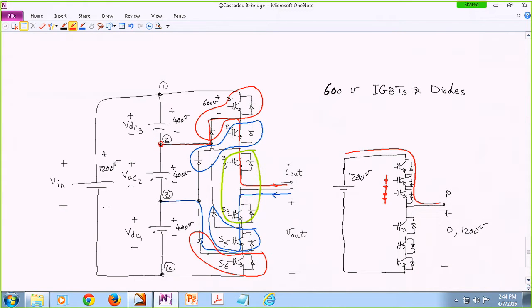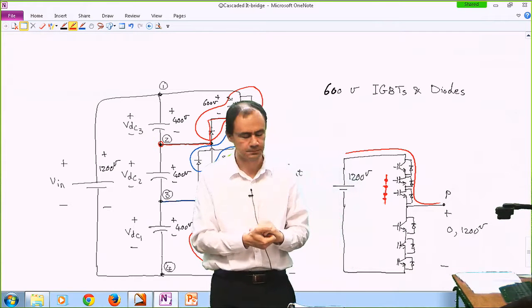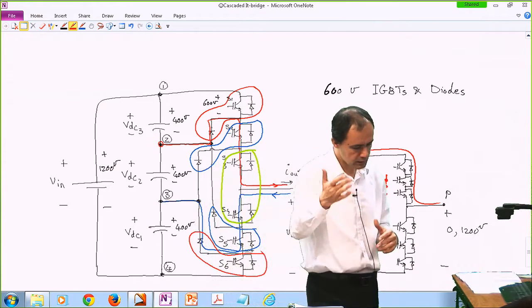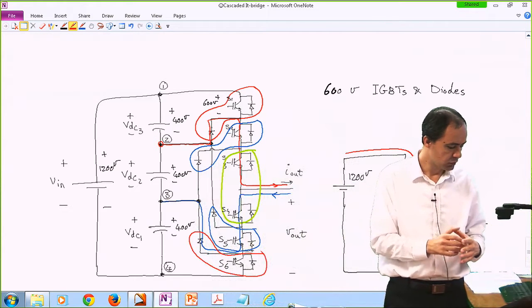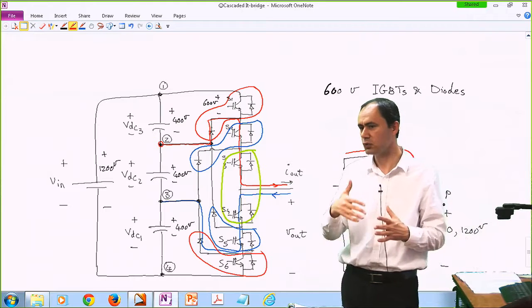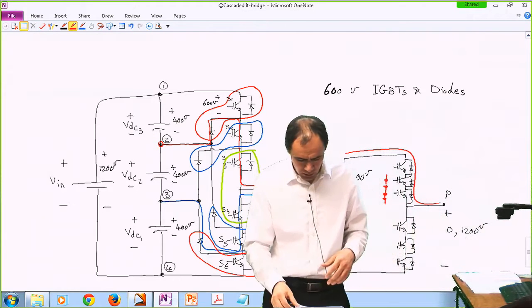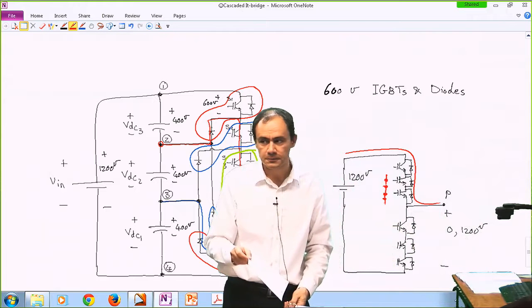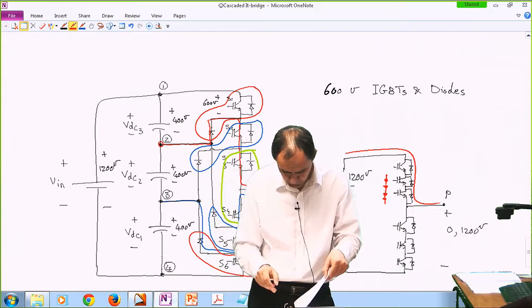So technically you can achieve putting transistors in series with each other. It's not as reliable as a multi-level topology, basically. And in a multi-level, I mean the converter that I have on the left, you only added 4 diodes and 3 capacitors, and then as well as 2 extra levels for your voltage, which is better. Any other questions? Okay. So let's move on.